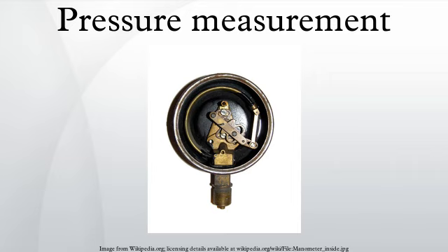Mercury is pushed down the tube farther than it would if only measuring still air. For a plane traveling around 129 m/s, the dynamic pressure adds about 10% to the atmospheric pressure at sea level. A U-tube for measuring dynamic pressure on an airplane would be impractical, so a pitot tube is used instead that relies on a diaphragm rather than columns of fluid. Although dynamic pressure can be measured directly, fluid speed and air speed can be measured indirectly using the Bernoulli principle if both dynamic and static pressures are known.